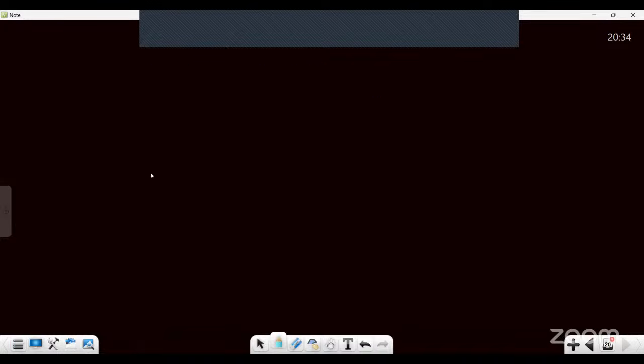Now, when pure SiO2 is there and there is no CaO, suppose I am talking about a slag where we haven't added any flux, we haven't added any lime, that is CaO. At that time, what happens? The activity of the silica in the slag is going to be very high.